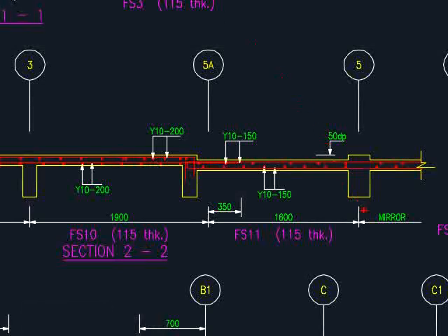In the case that you need to mirror the sections, there are two options that you can do. You can draw the entire sections, that means you are repeating these sections again starting from here, or you can clearly indicate the mirrors. Make sure it is properly indicated so that the contractors know its meaning.